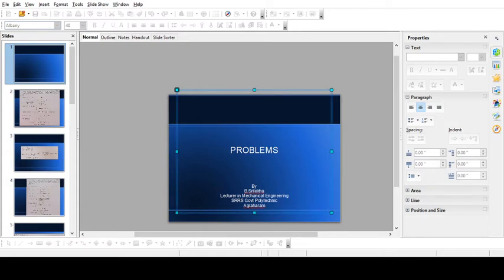So you can write it as 27 into 10 to the power of 3 newtons. Next, the gauge length L is 80 mm and delta L is 0.12 mm. Next, delta D is 0.007 mm. Now we need to find Poisson's ratio 1 by m and the modulus of elasticity.